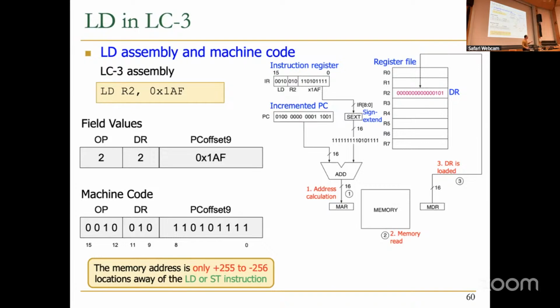Well, the memory addresses are unsigned. The address is unsigned, but the offset is signed so that you can have a relative value. If your relative value was unsigned, you would only go either forward or backward. You cannot go backward and forward, right? Make sense? Okay. But the address itself has no sign to it because it's really a linear array that grows from 0 to 2 to the n minus 1, where n is 16.